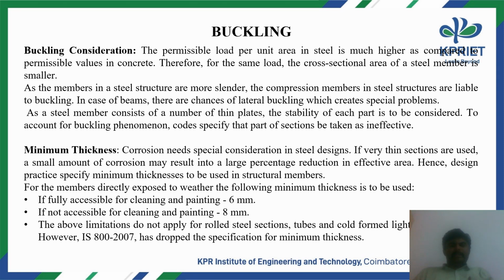And then the second criterion is minimum thickness. Corrosion needs special consideration in steel design. If very thin sections are used, a small amount of corrosion may result in a large percentage reduction in effective area. Hence, design practice specifies a minimum thickness to be used in structural members.